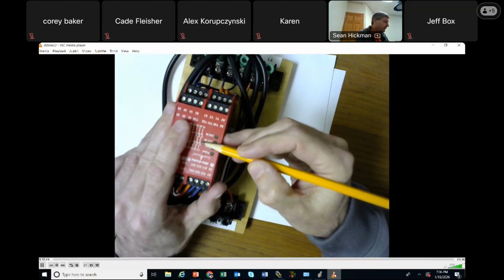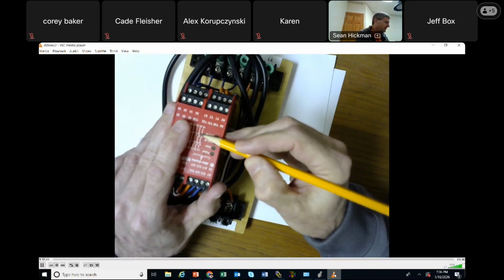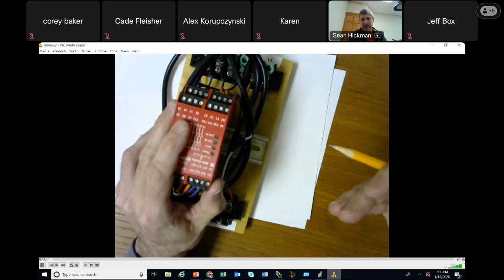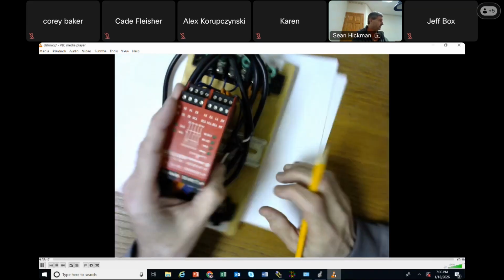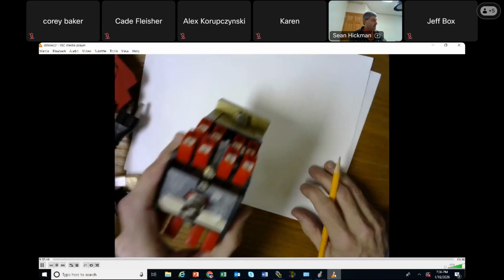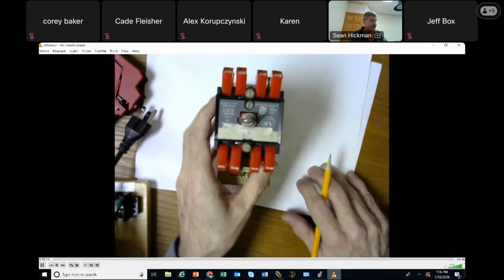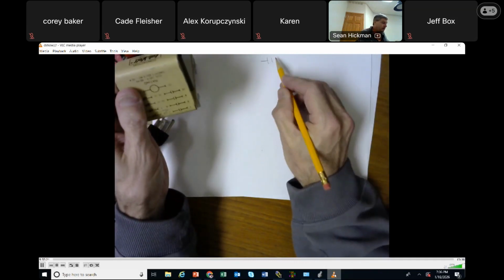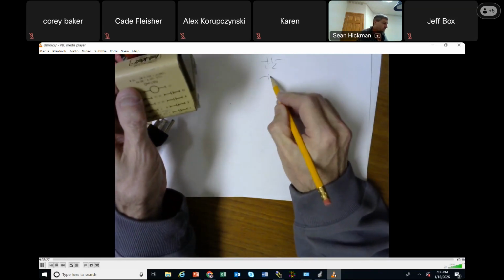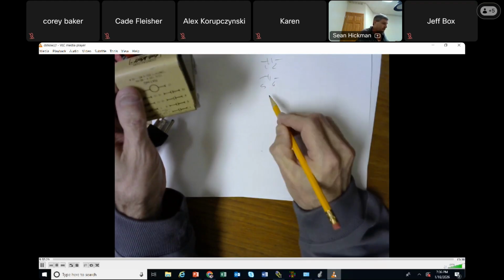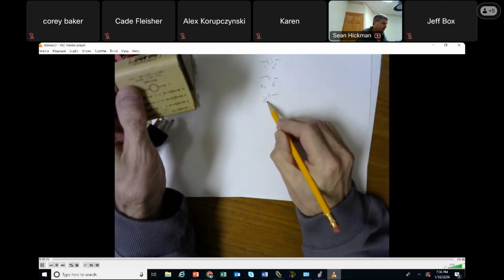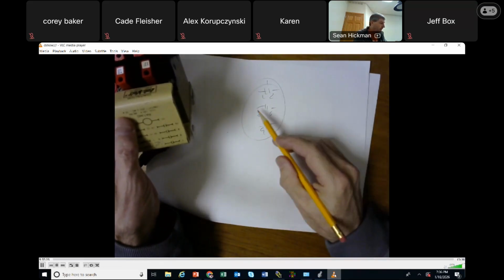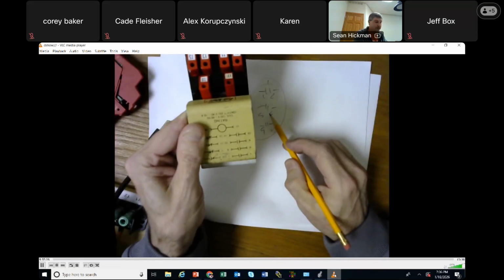This looks like 2, and this is 2 and that's 2. They're just redundant contacts. So when I turn this relay on right here, I get right here. It says 1 and 2, 5 and 6, 9 and 10. These close, right? This gets multiple contacts to close. 1 and 2, 5 and 6, 9 and 10, 13 and 14.